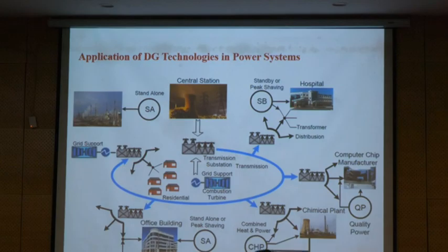And in some cases, when you have a nonlinear load, it produces harmonic components, which cause a lot of problems for the grid. But you can tune your controller so that it provides just the harmonic current of the load, and the rest of the power can be compensated by the grid. By this, you can reduce these disturbances and increase the quality of the system.